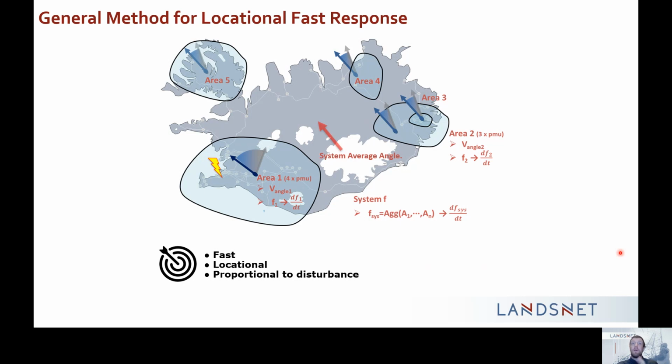The goal of this is, of course, fast detection, and when talking about fast, you're not talking about protection fast, but within half a second. Usually it triggers around 200 to 300 milliseconds, but usually we're getting a response from the response providers between 500 milliseconds and a second.